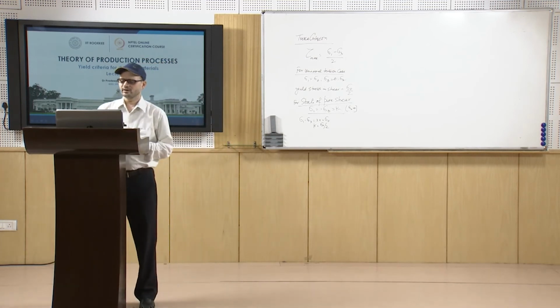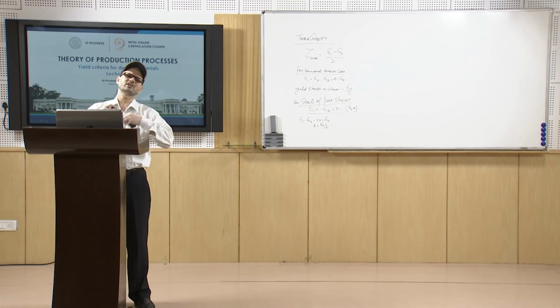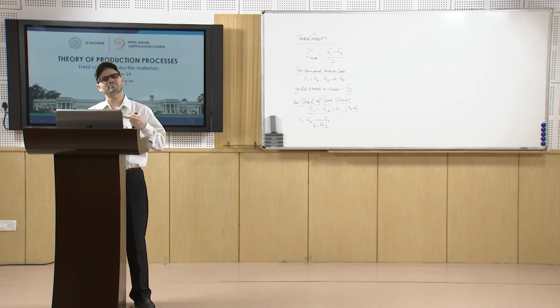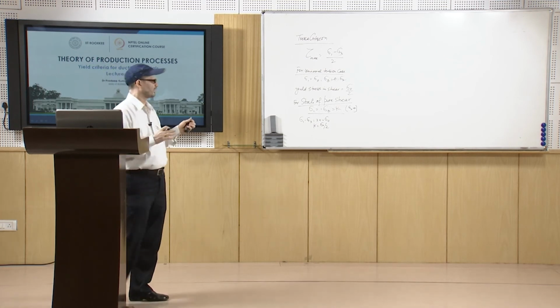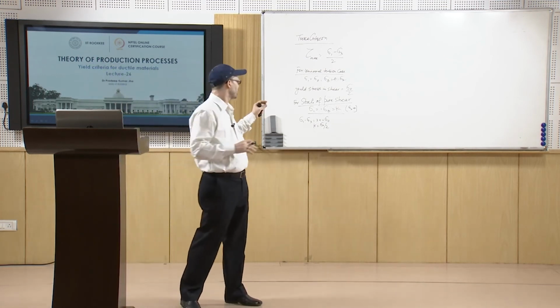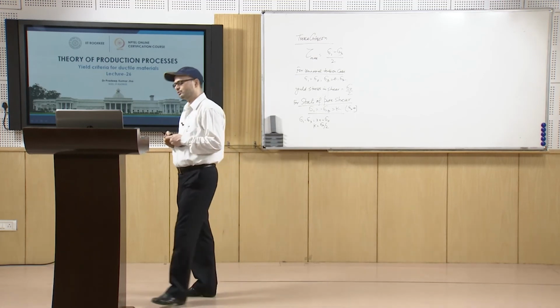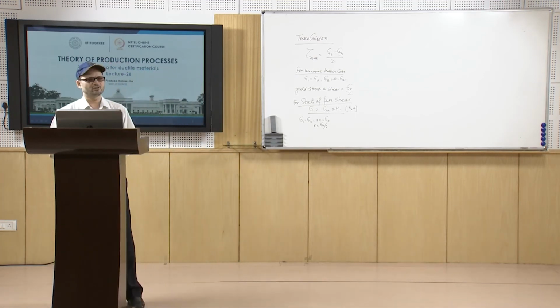in case of Tresca, and you can write that sigma 1 minus sigma 3 equal to sigma 1 prime minus sigma 3 prime, that will be equal to 2k, because being the invariant function this will be equally valid for any situations, any angles or so.